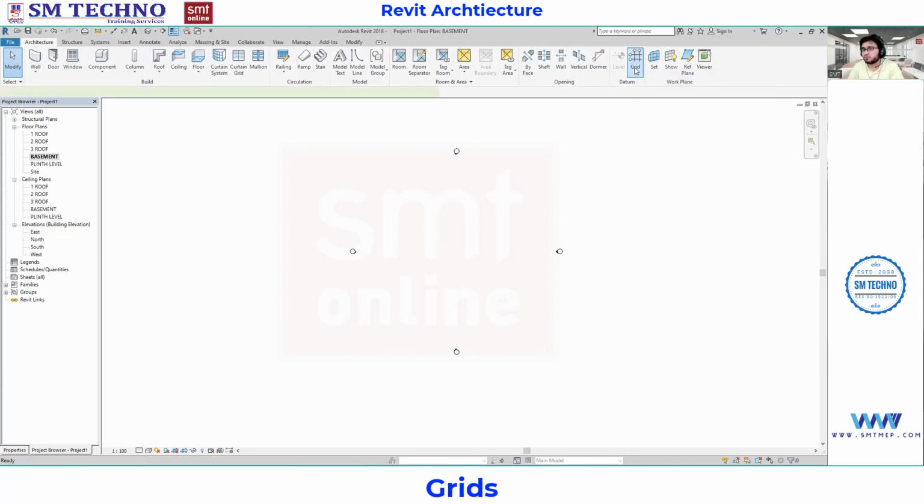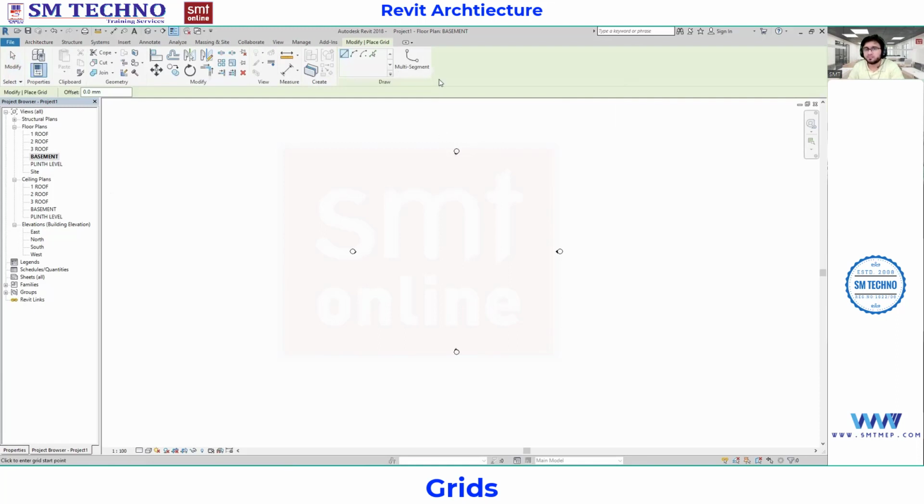Select the grid from here. Now provide the sketch. Wherever you want, you can place it now. Here you can see the drawing toolbar. We have got some options, so as per that we can select and place. Here we have got a line, the three-point arc, the center and two-point arc, and we have got a pick line also.